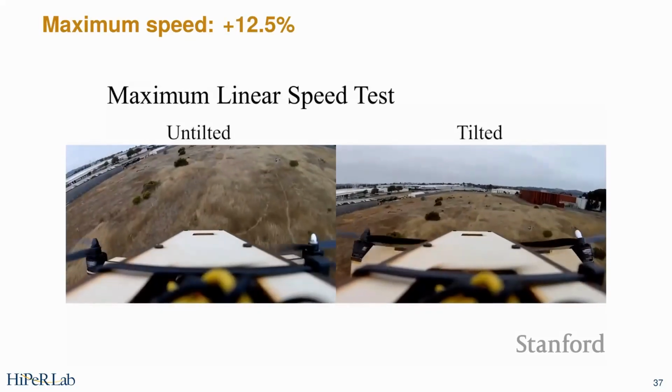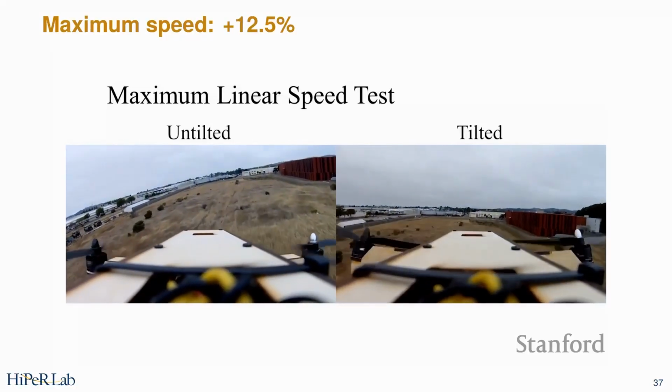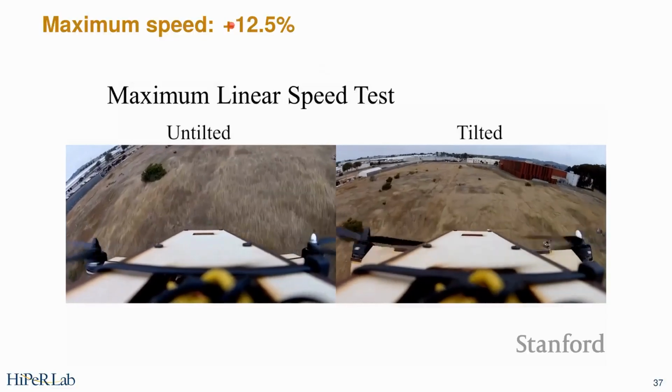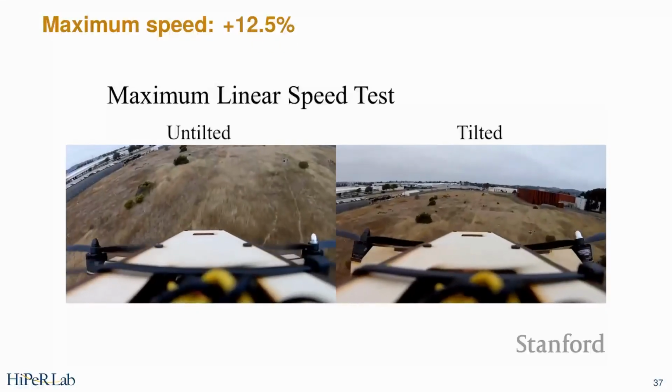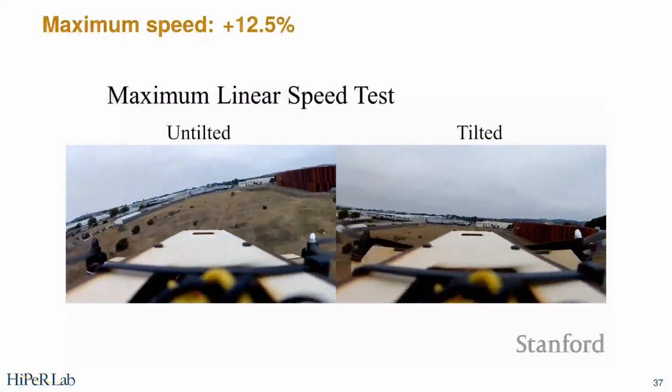But what this gives us is much higher maximum speed, for example. So here we have the system with the tilted configuration on the right and the untilted configuration on the left. And we can achieve sort of a 12% faster flight. I forget what the efficiency number is at the same speed. You can also show something like 10, 15% decrease in energy that you require while flying.